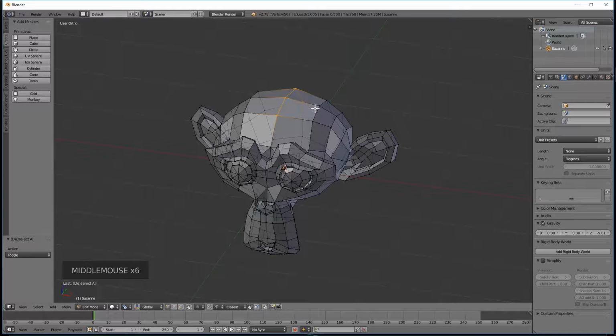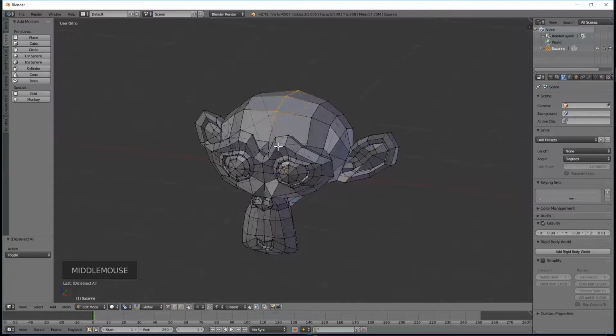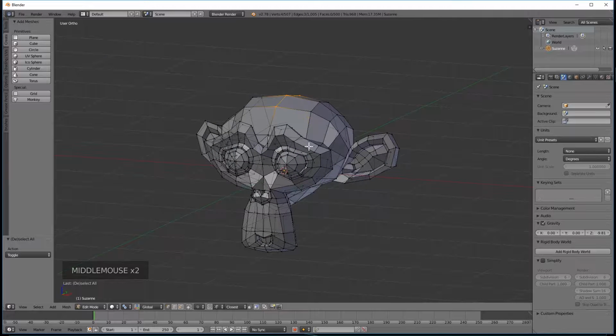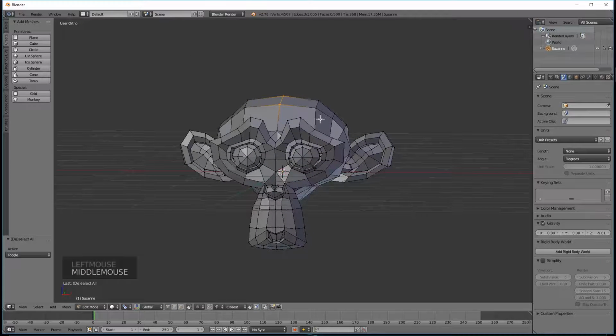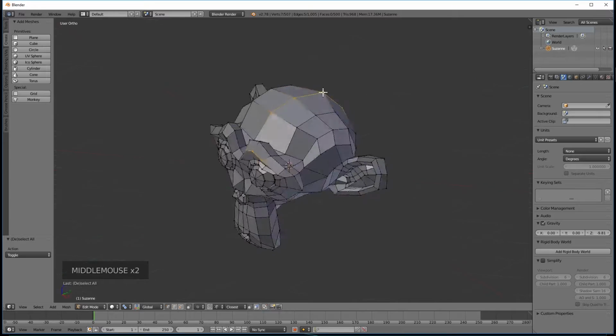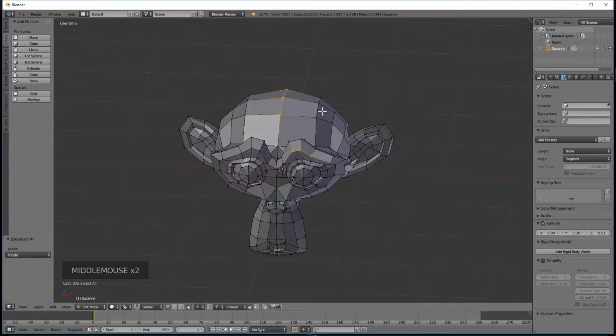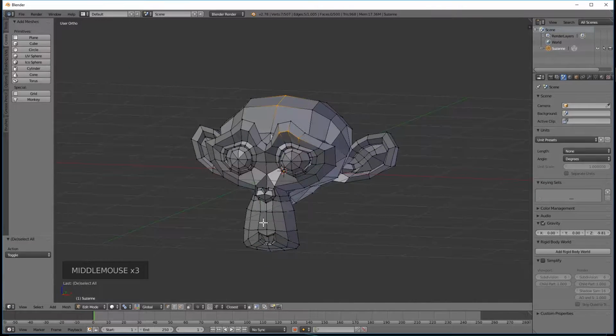If you don't want that, and sometimes you won't, sometimes you'll only want to be selecting things that are visible. Say I want to select these points, but I don't want to get all this other stuff behind it, I would turn this on so you can't see through it anymore. Let's go Control, left click and drag, and then I just got those points. Nothing behind it was selected, except that stuff I already had selected. So this is basically limiting selection to visibility.